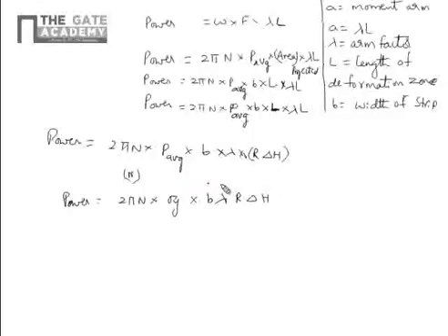Sometimes they give the pressure developed, sometimes indirectly the stress developed or yield stress, because rolling is a plastic deformation and a forming process. So it has to be at minimum the yield stress and at maximum less than the ultimate stress. So they give the minimum yield stress. So this is the final formula for power required for the rollers.